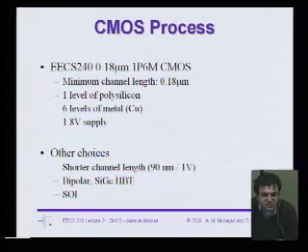So if you want the best silicon germanium process, you probably have to go to Jazz or IBM. And you don't have that much negotiating power because there's just not that many other players that can give you that performance. But if you're talking about CMOS, you can negotiate. So that's another reason why CMOS ends up being preferred.